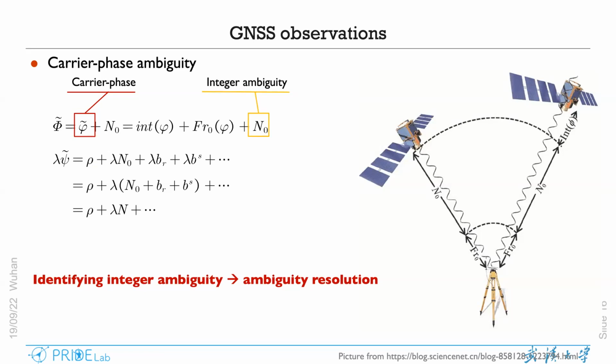So we have to tolerate these ambiguity terms before we can do high precision positioning. And here we need to introduce the term phase bias. The phase bias means we have some things that we don't like in data processing, because the least squares adjustment cannot distinguish between integer parameters and non-integer parameters. N0 is an integer parameter, but we have some other errors assimilated into the ambiguity.